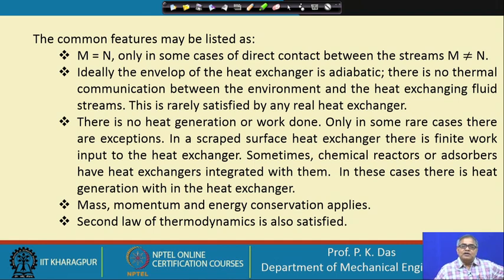Ideally, the envelope of the heat exchanger should be insulated, but in most of the cases it is not, in a practical, real heat exchanger. There is no heat generation within the heat exchanger, but if there is absorption or some sort of reaction, then there is heat generation. And in very few heat exchangers there is work input because some sort of agitation is created in the fluid.